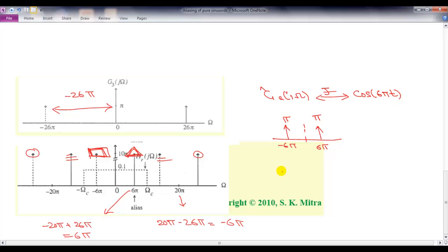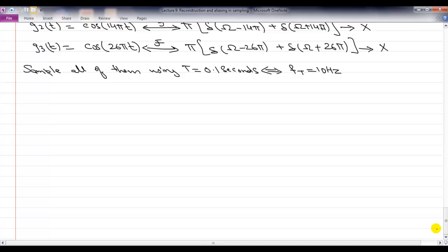So this is an example where again your frequency is aliased, and the alias is now completely different from the previous case, but you end up with a signal which looks exactly the same as the previous case. In this example, when you had a 7 hertz frequency, that mapped onto 3 hertz. When you had a 13 hertz frequency, that mapped onto 3 hertz. Is there a formal description of how this mapping happens?